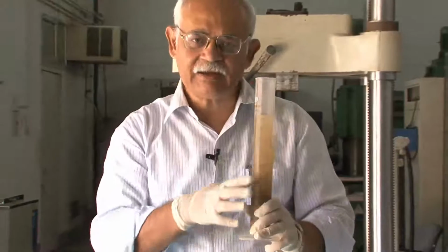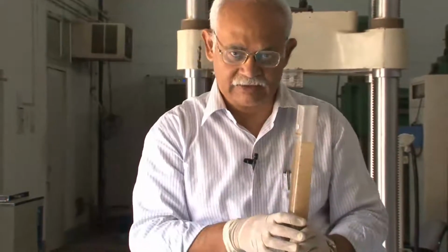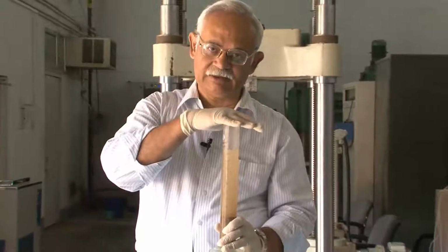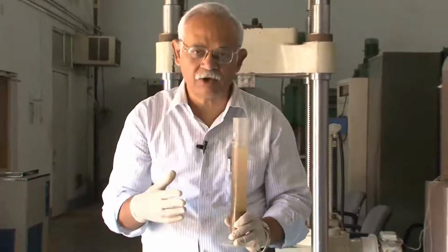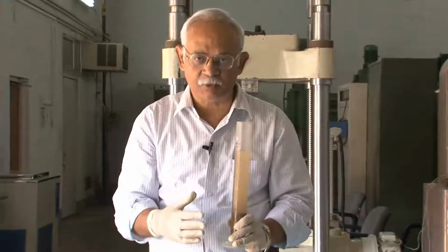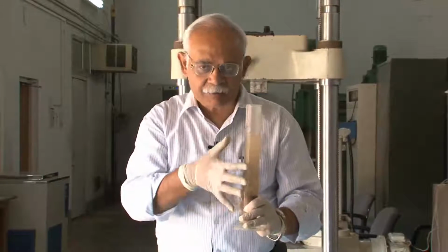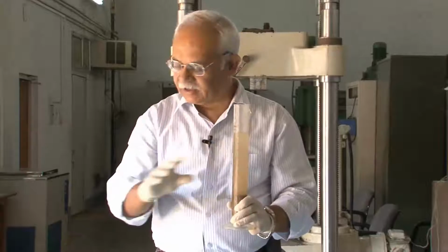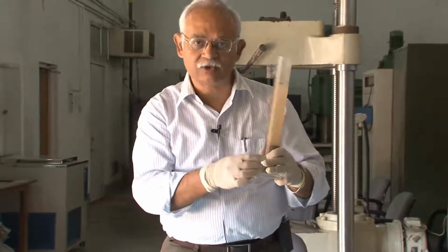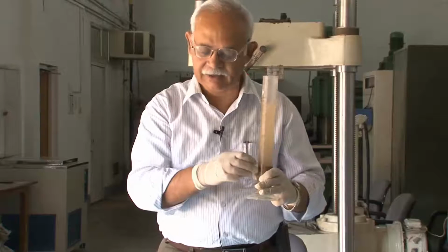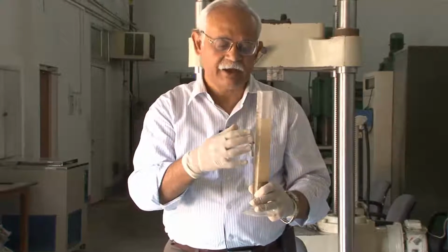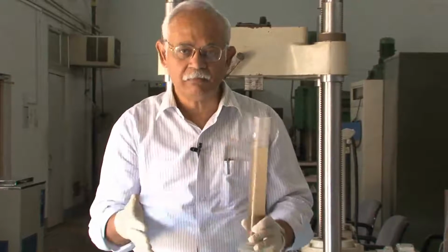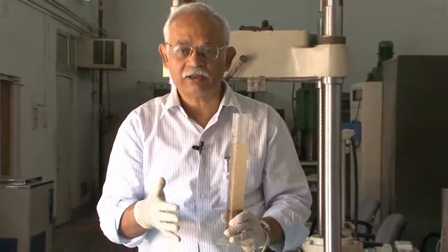So, basically what we talked about in the class was that if we want to fix the volume of this container, which we took to be 1000 liters or a cubic meter, the proportioning exercise really boils down to how much water should be there, how much aggregate, the coarse aggregate and the fine aggregate should be there, and how much cement should be there, in order that their total absolute volumes become a cubic meter or 1,000 liters.